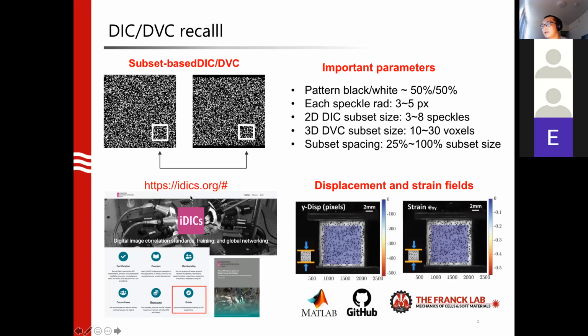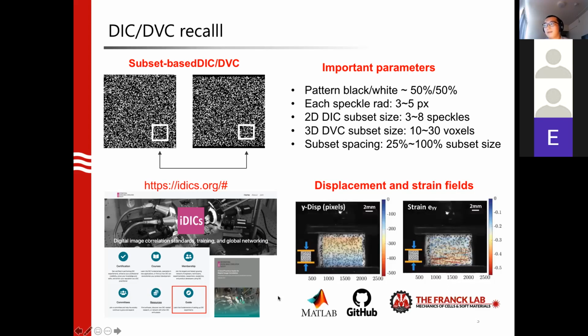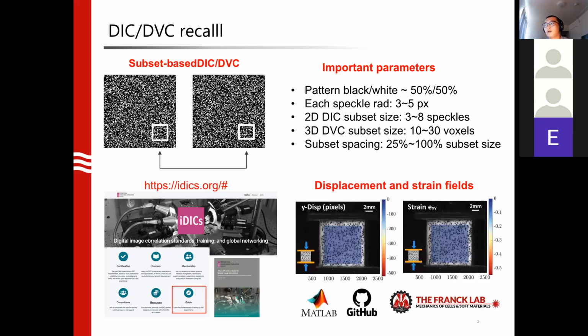There are lots of useful resources you can always look into on the IDIC Society website. There's also a very nice guidebook. And finally, what you are always solving for is the displacement field and the strain field. Imagine if you also know the materials model, right? Then you can plug in the material properties, and you also know the stress field. So this is what we did yesterday.